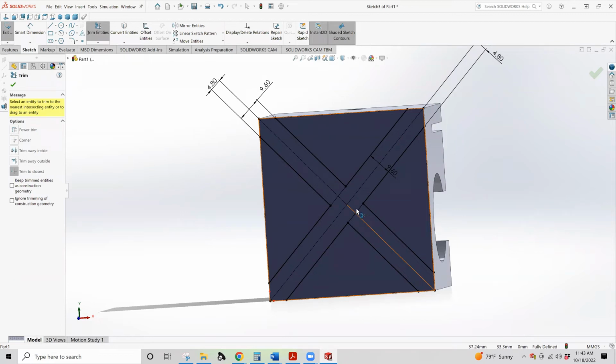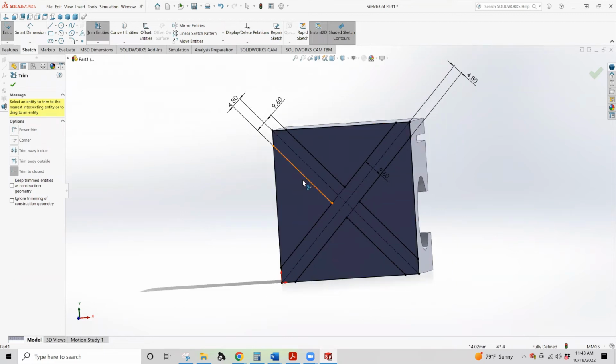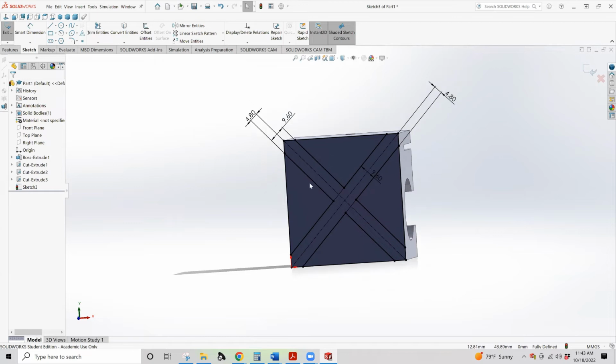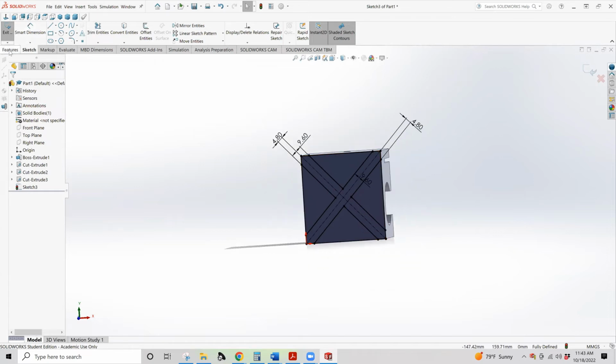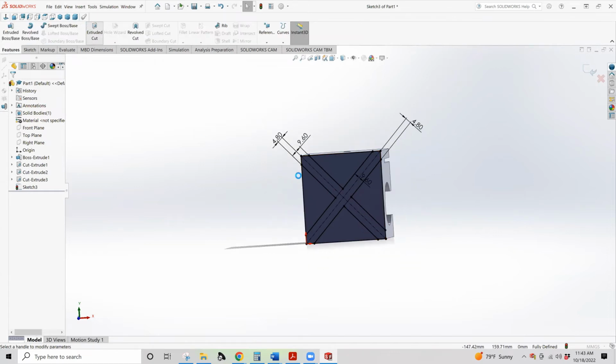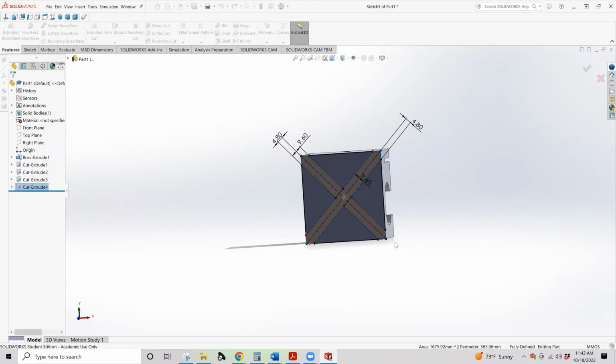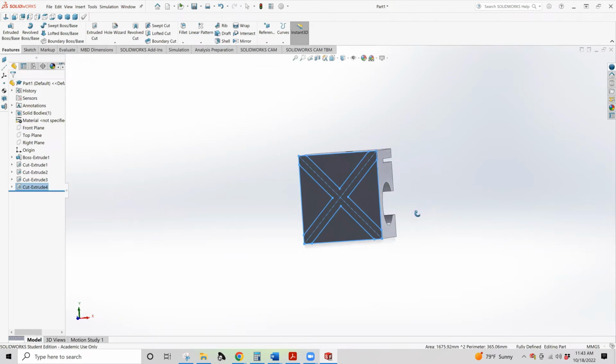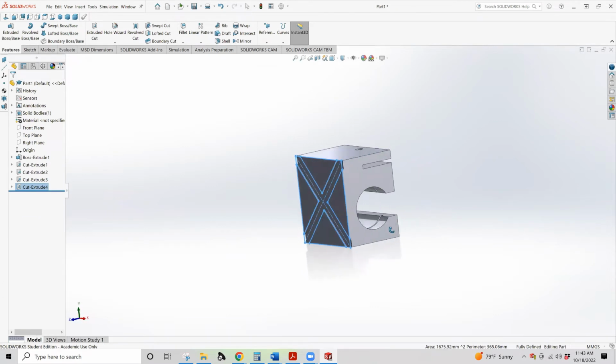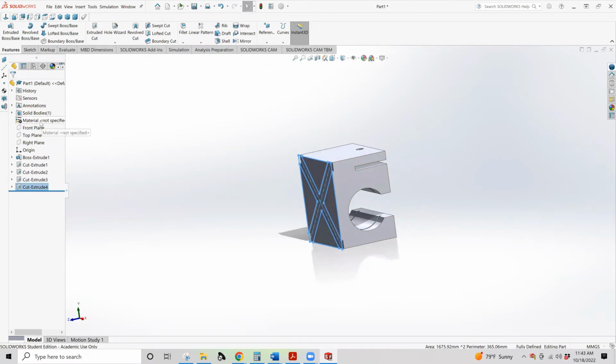Now we have a couple of those leader lines in there. We don't need the deselect tool. We stay fully defined in the sketch. And we do our extrude cut of this interior region about 1.5 millimeters, just like so. And we have created our part.